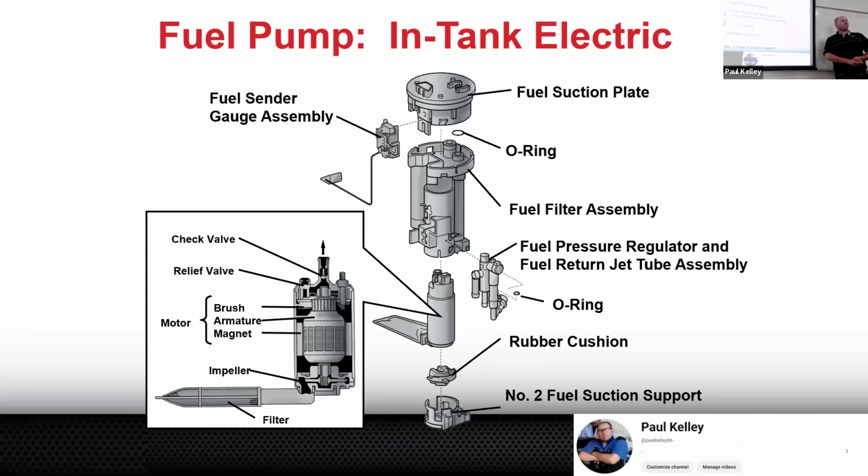You picking up what I'm putting down? There's an access panel now, but the only thing is if you're going to cut it, you're cutting it with an abrasive like a cutoff wheel and you're throwing sparks all over that fuel tank. Hope you don't have any leaks, especially if it's a metal tank that's kind of corroded and has pinholes. You may have what the manufacturer would call a thermal event. All right, makes sense. So, good overview.